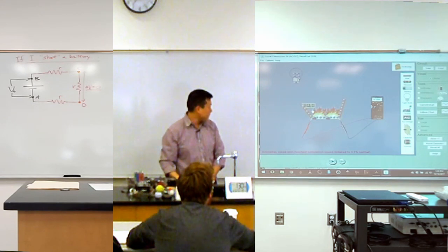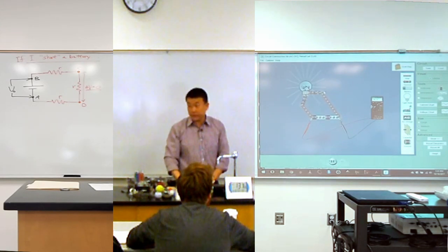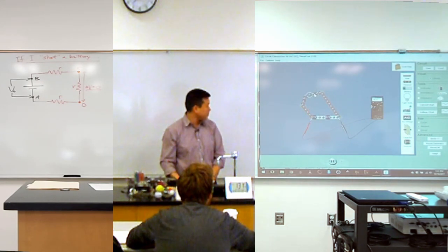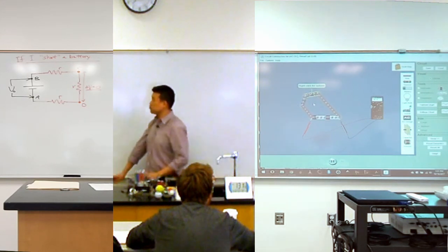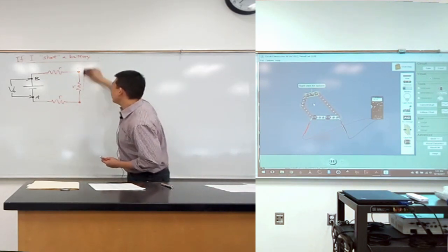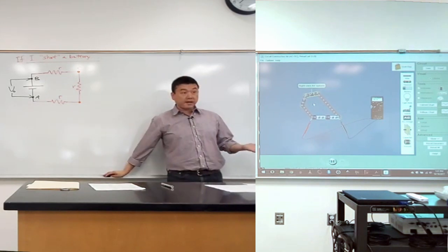I can actually imagine that the wire that I'm connecting to this light bulb with, it actually has some resistance. So it's in series with some resistor. So it lights up the light bulb, and these resistors actually slow things down a little. I can model things that way. With that model, everything would be correct, or you wouldn't have any contradiction with anything. Because when I quote unquote short this battery, then this resistance still makes things slow down. All the voltage drop happens over these resistors, and you wouldn't have this statement here, and everything will be consistent with how you would analyze the circuit.